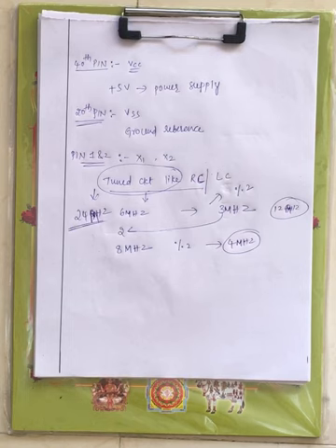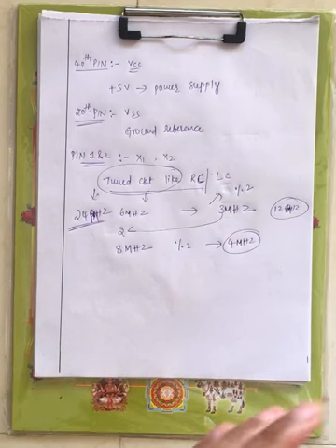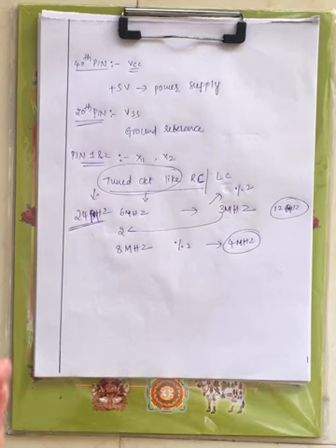Oscillator is nothing but the tuned circuit like RC or LC at your pin number 1 and 2. Now what will the oscillator do? It will generate some oscillator frequency. That frequency is divided by 2. This operation is done by the internal clock generator of the processor. If the oscillator frequency is 8 megahertz, divided by 2 it is 4 megahertz, and at this frequency the processor will operate.